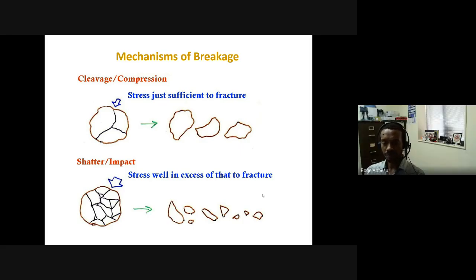And for example, if you ask me about making roads and things like that, that's how I would probably recommend you to crush the rock, so that you produce lots of smaller rocks which are now intact, which have resisted the excessive force applied to them, and do not have residual cracks inside them, and therefore this will be ideal for making roads.